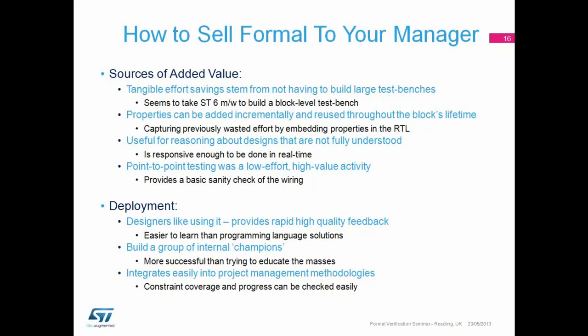Formal is very useful for reasoning about designs that are not fully understood. Like I said, the methodology is responsive enough to be done in real time. When we've used very heavy program-based approaches, so SystemVerilog or C-directed tests or whatever, typically the amount of code that you have to write in order to prove a property or to check an idea is significant. So it's not really something you can do in real time. Whereas we found that Formal was responsive enough to do this in real time. And like I said, check out the point-to-point testing, because that for us was a big win, very low effort.